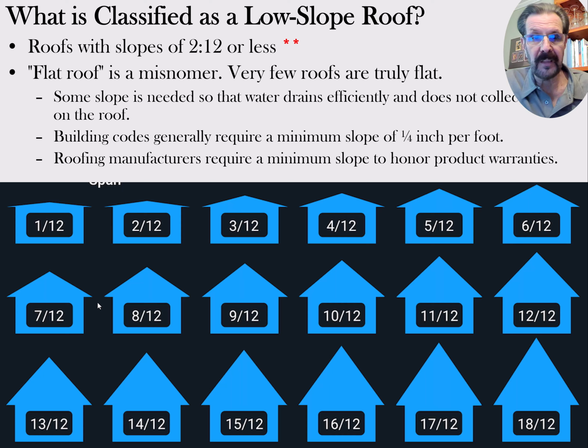So the building codes allow you to go down to as little as a 2.5:12 slope. That means 2.5 inches up for every 12 inches horizontal. And so how does that square away with your warranty? It doesn't really. What happens is that on the building code, they will require you to double up the underlayment and cut the reveal of the shingle down so that you have less shingle revealed. So that means you have to have more overlap. That takes more shingles. So what they do is they cheat on both ends, and they get a kind of mediocre result.